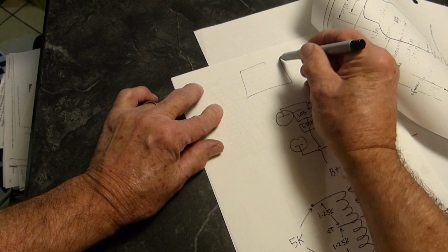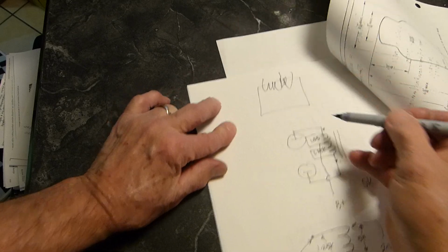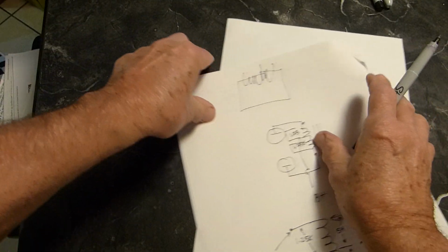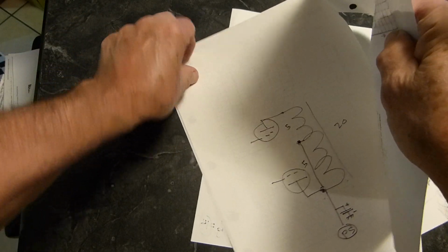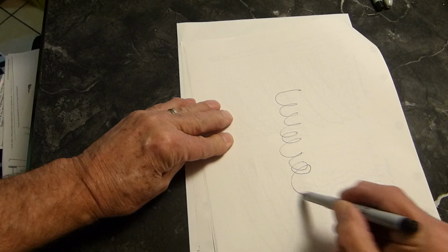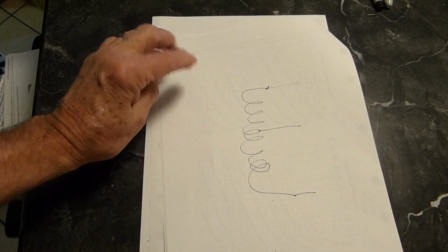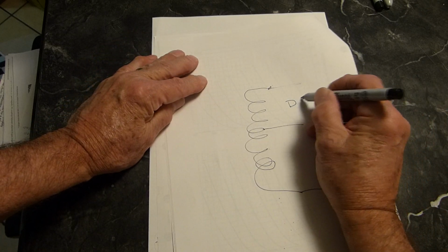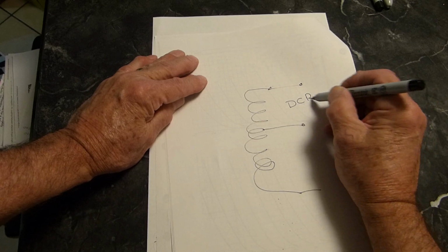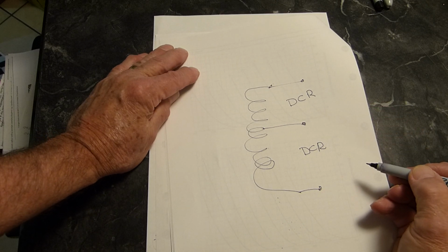If you take a big output transformer, and this is the primary winding with a bajillion turns on it up here, and you measure its DC resistance. I gotta do this again. I can do better than that. If you do the DC resistance of it, there you go. Now that's a real transformer, isn't it? And here's its center tap. If you take a very accurate ohm meter and you measure DC from here to here, and you measure DCR from here to here, they're going to be slightly different.